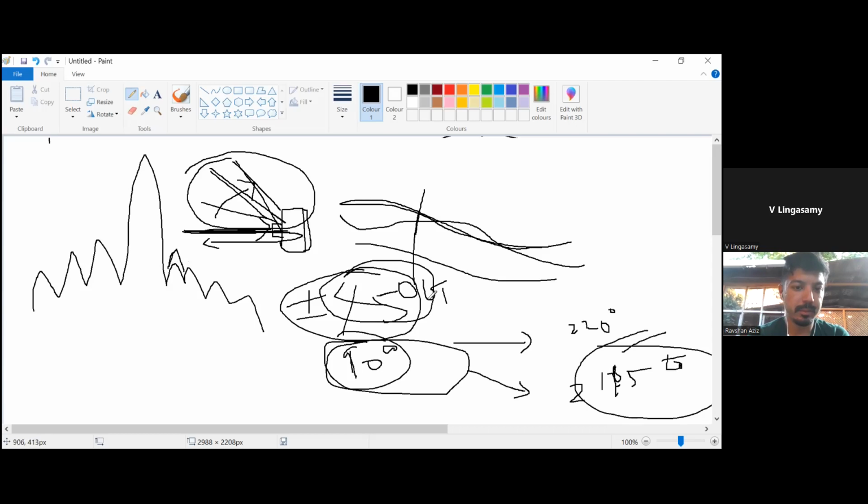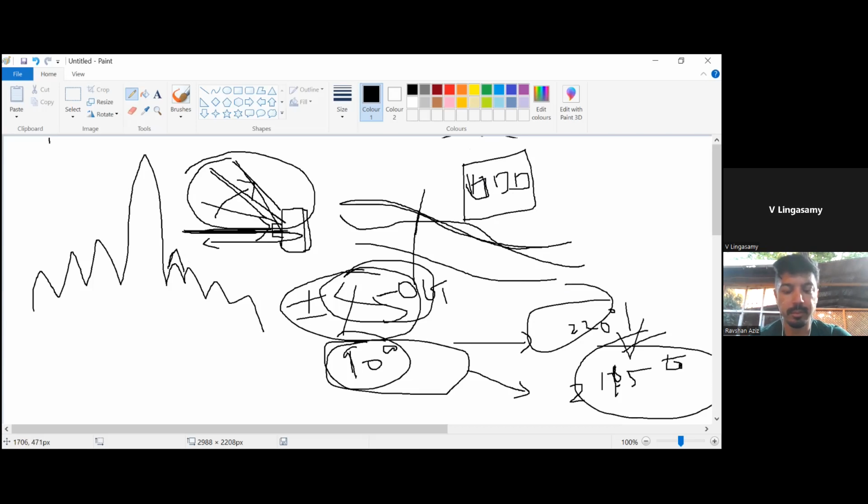When you start increasing the angle of incidence, you are going to compensate the phase in the overall structure, for example, a reflector or impedance surface. You have a constant phase distribution, but the unit cell is going to offer different phase shifts. For example, instead of 220-degree, I may get 265 or 195. Due to this offset, it will affect the radiation pattern. The radiation pattern will be like this also.